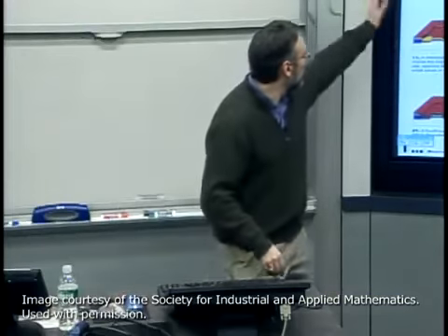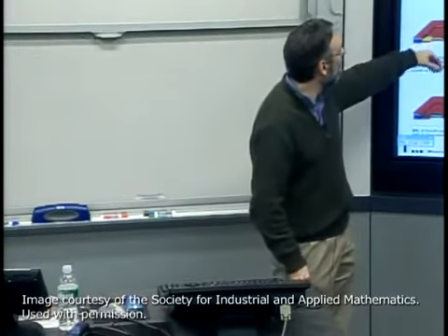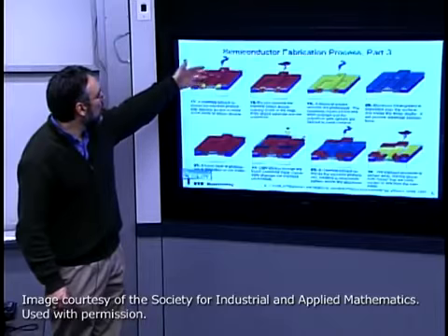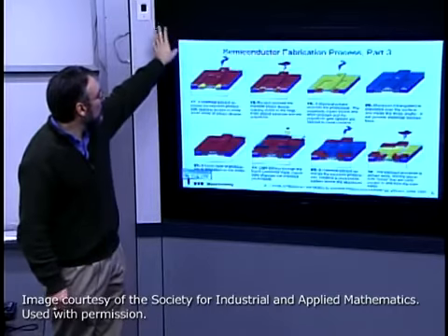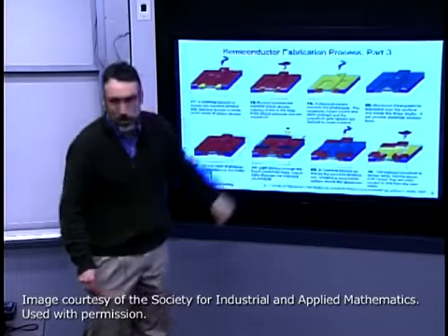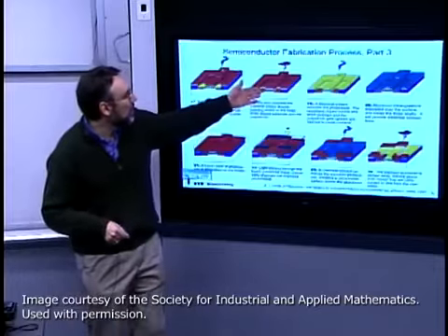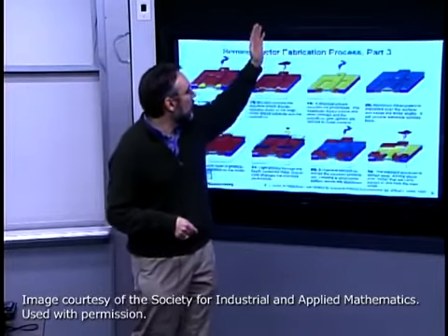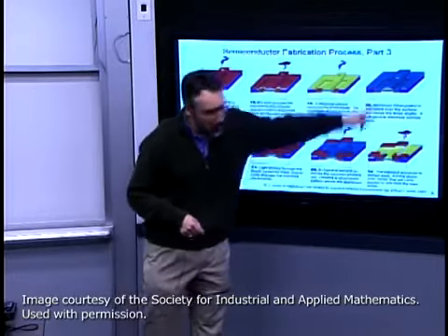So we go through again, photolithography, put our resist down, expose it, develop it, plasma etch, again controllably etching through the oxide, stopping on the silicon layer, remove the photoresist, and now we put down a metal layer.